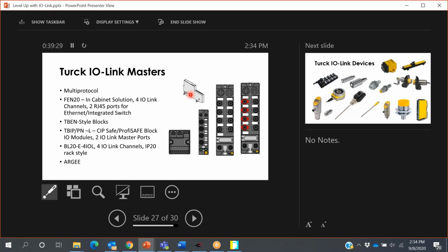Well, then these other 2 connections, since we didn't need any more IO-Link connections, you can tell that IO-Link port that, hey, now you're a discrete input. And so we ended up putting the inputs down here. We used the extra output on all 4 of these. And so now we did 2 push buttons, 2 IO-Link sensors, and 4 discrete outputs, all with the one block. And then RG did the crane collision avoidance logic. So without having to buy any enclosures or buy a separate PLC, they were able to do that simple function of collision avoidance and then appropriately stop the contactors.